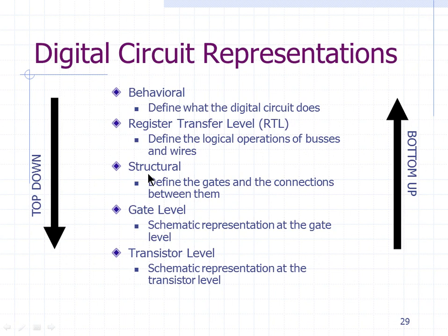That's called structural design. And then we have behavioral design, where if I say C is equal to A plus B in Verilog, that will implement the adder for me, because I'm saying A plus B. So that is the behavioral way of defining Verilog. So in Verilog, we have two levels: the behavioral method of designing and the structural method of design.